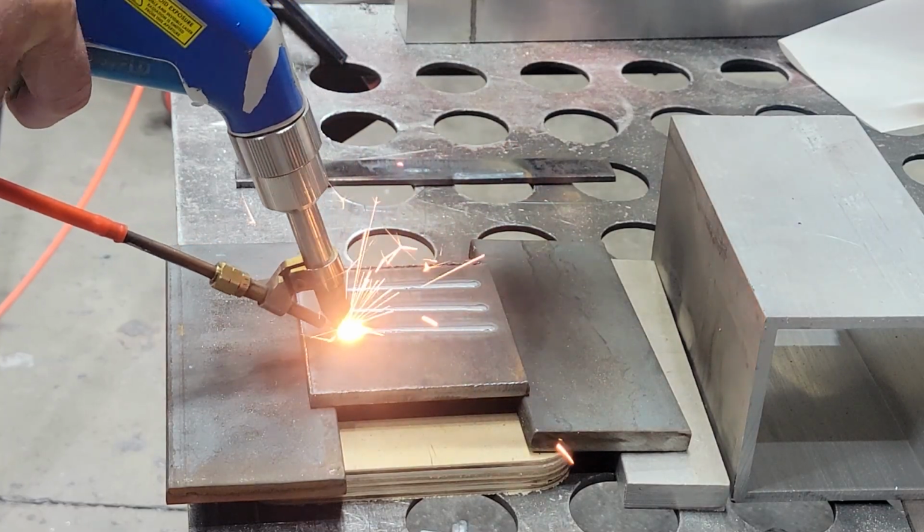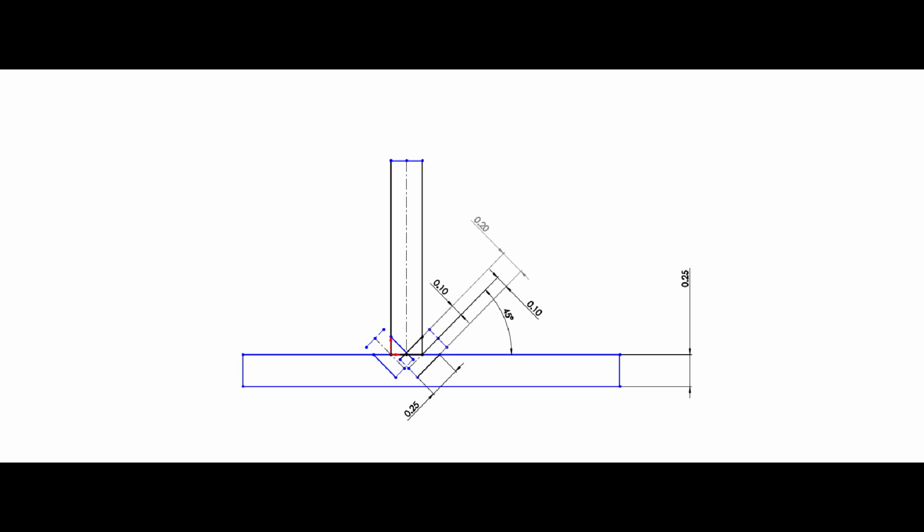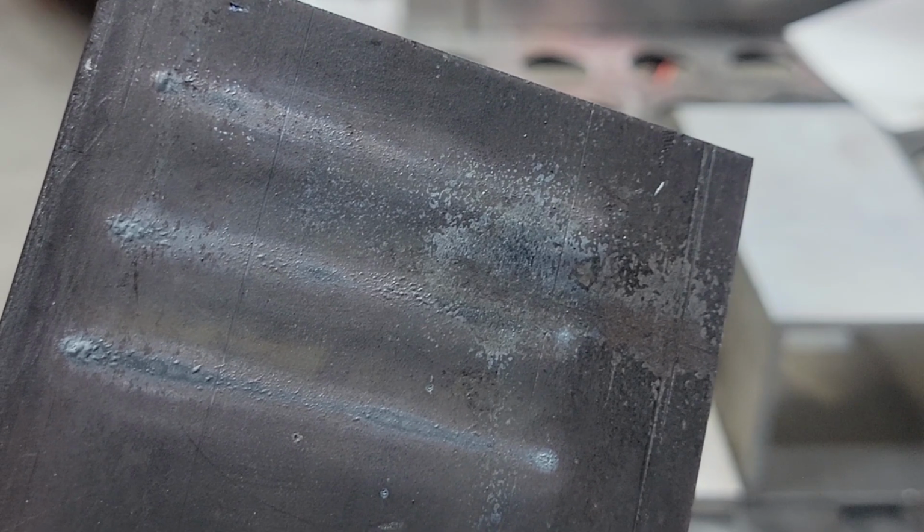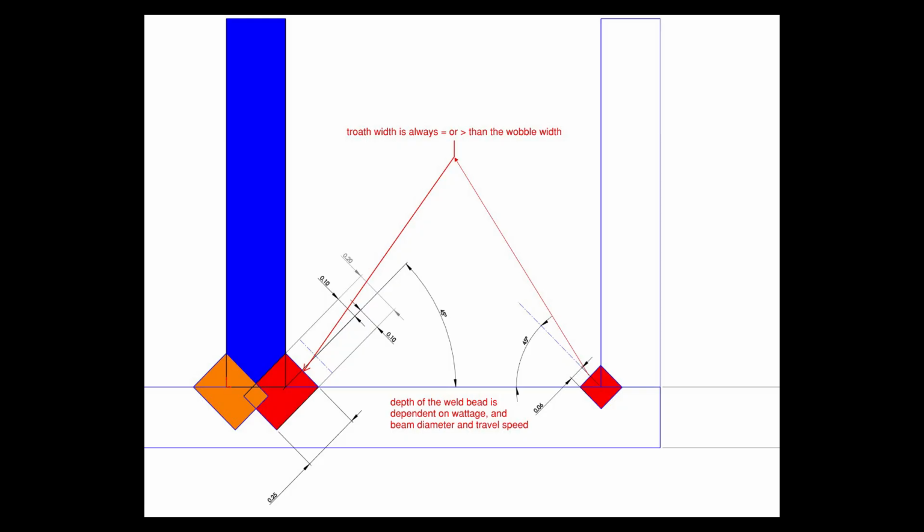A critical distinction lies in weld bead cross-section geometry. Laser welds produce a rectangular or square cross-section, reflecting the uniform energy distribution of the focused beam. Conventional welds produce variable, drip-shaped cross-sections, often wider at the crown and tapered into the root.